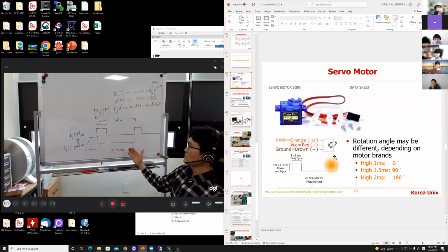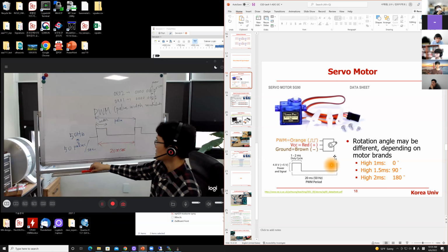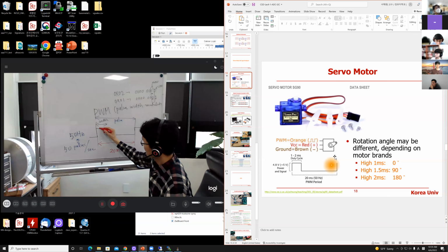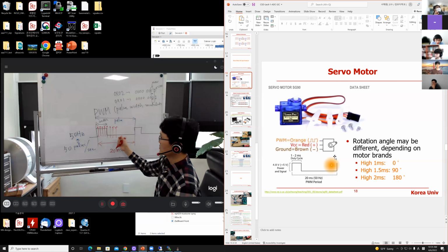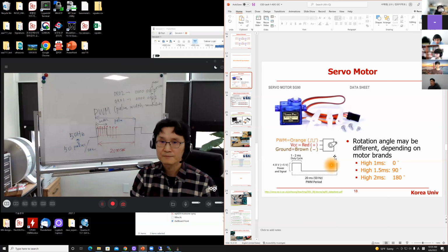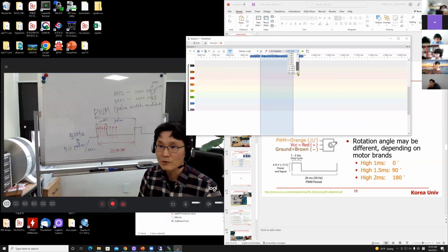Then the logic analyzer is trying to probe that signal. How it works is it is trying to sample that wire, the yellow wire, right? So how frequently you have to sample this is specified here, 20 kilohertz, or you can scroll it down, right? You can go up to 48 megahertz. That is the sampling frequency.